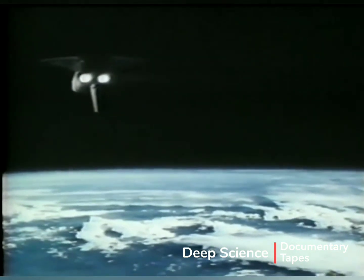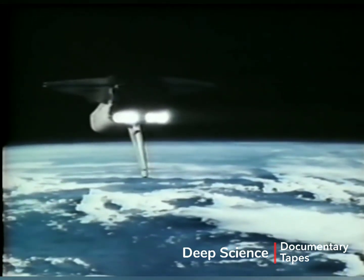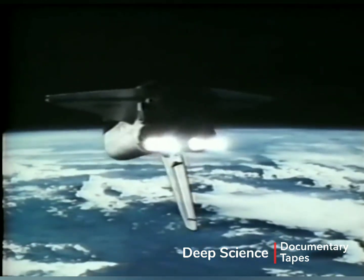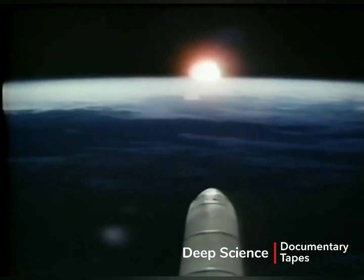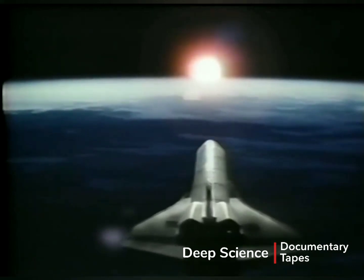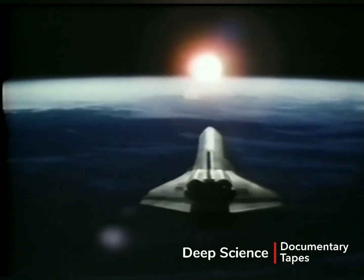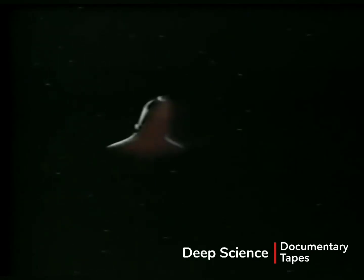When the space shuttle completes its orbital mission, it executes a precise retrograde burn to initiate its controlled return to Earth. This burn occurs nearly halfway around the Earth from the landing site. The new orbit established by the retrograde burn causes the orbiter to enter the Earth's atmosphere about 4,000 miles from the landing site. During the period the orbiter descends from its orbital altitude to atmospheric re-entry, its attitude is maintained by the use of reaction control jets located in the nose and tail of the orbiter.